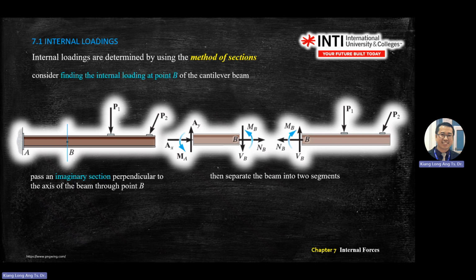Okay, you assume every time you cut, you separate, there's the contact force always pointing out from the body. You assume first. Then later you do analysis, you get negative, means it's wrong. What you draw in your free body diagram is wrong. You need to flip the direction. You will get negative. Okay, so first force you draw on the split section is the contact force.